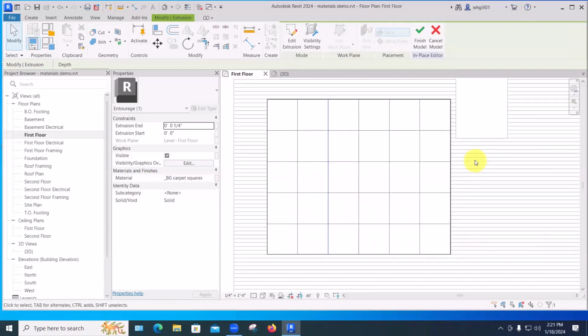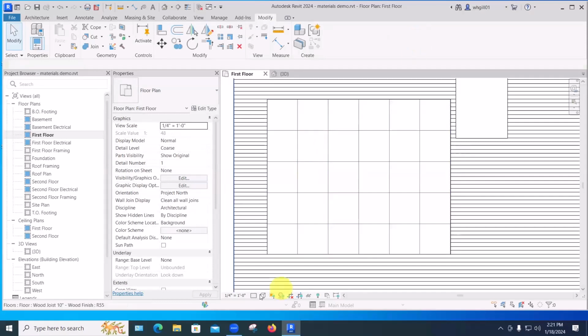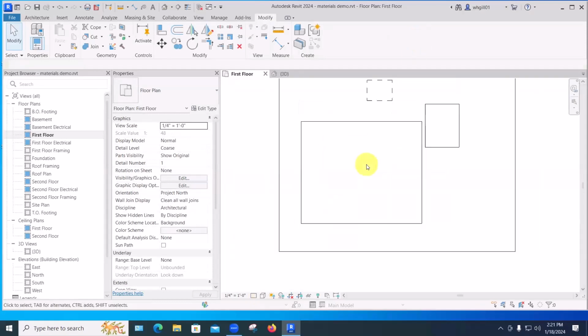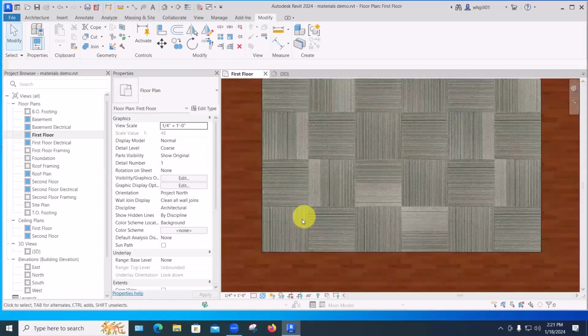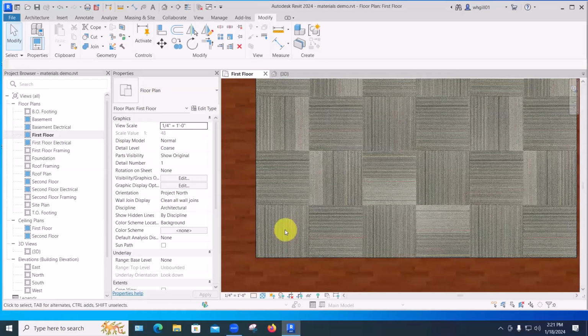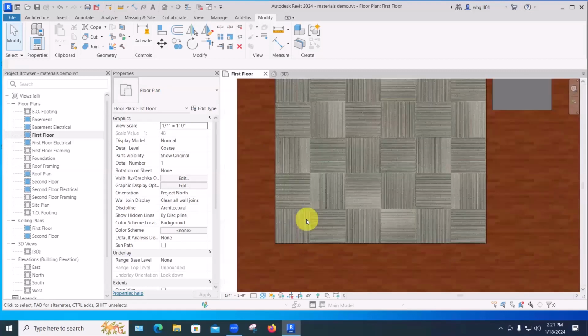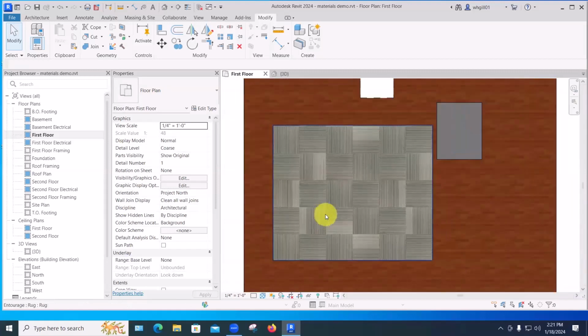With a lot of things like wallpaper, it doesn't matter, you just start somewhere and go somewhere. But with something like carpet squares, they start in some corner and go somewhere, or you center one on a wall or on the door or something like that. So then I'll say okay, and we can preview that here. Oh, we're back in the model, aren't we? Okay, so we'll just go to the textured view, and we can see that now these line up. They got moved, jogged over. It's a really nice tool.